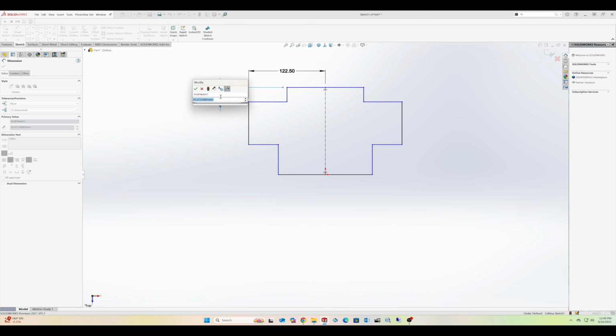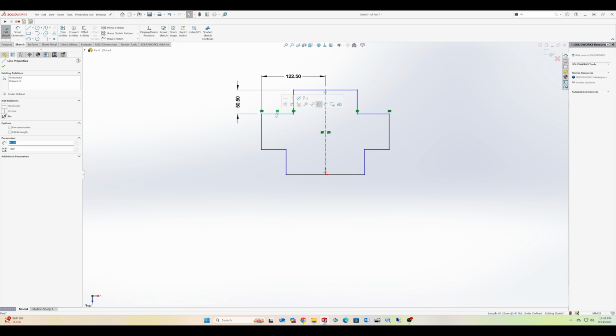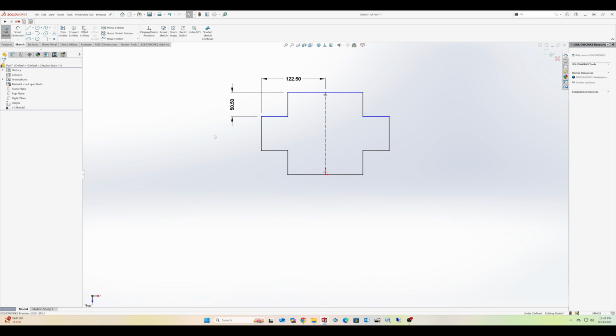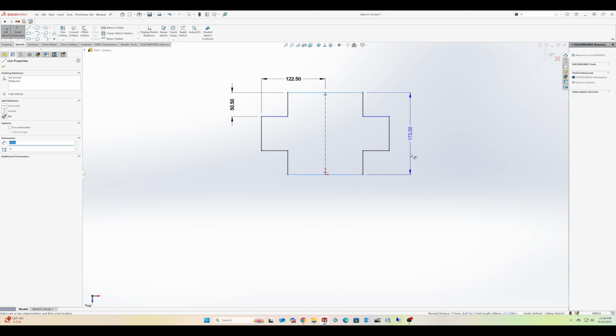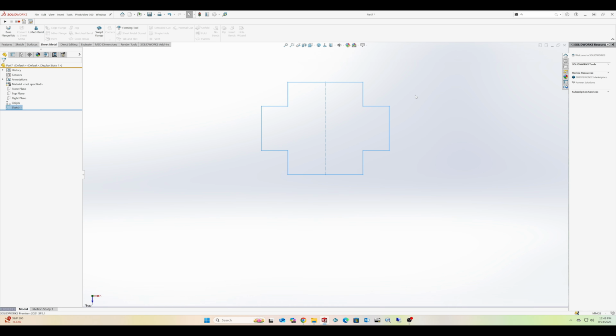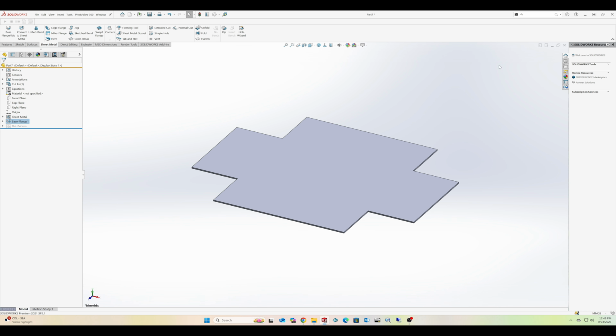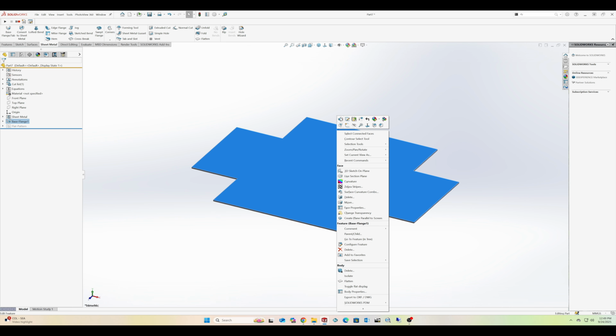And what the sketch to bend allows you to do is it takes that DXF that I'm creating here, and it allows you to apply bend lines to that DXF or flat pattern, which is basically going to be our base flange. It'll just be our base flange, but folded out. Once I get this completely drawn out, I'm going to create a box like we did in one of the other demonstrations with the edge flange, just to show you how you would get that from a DXF part.